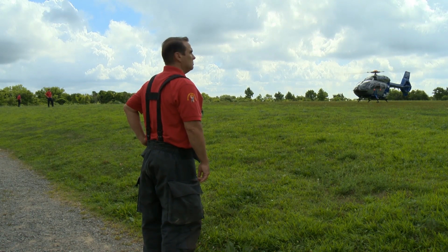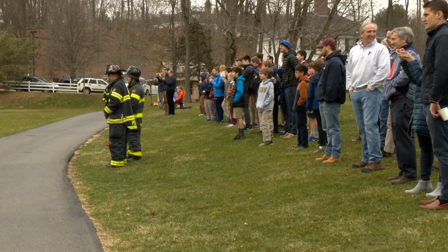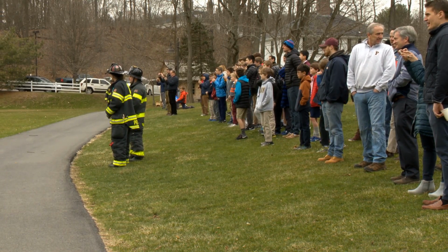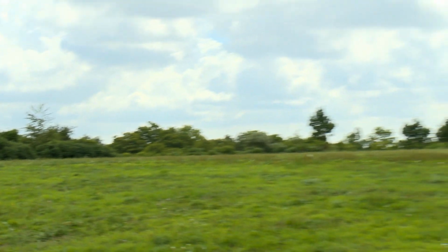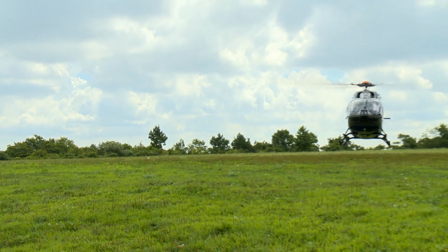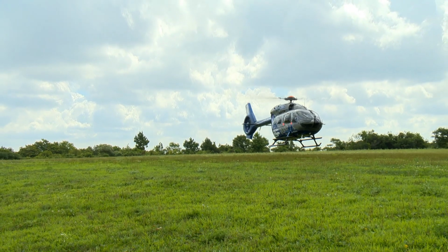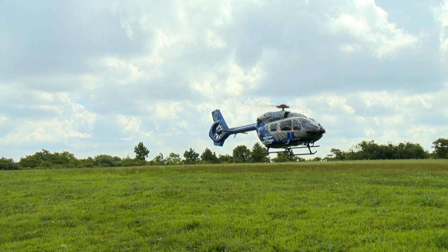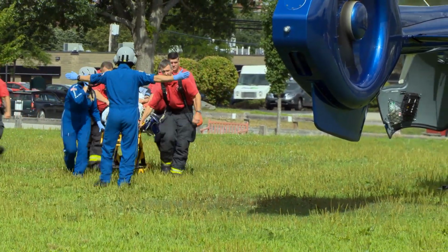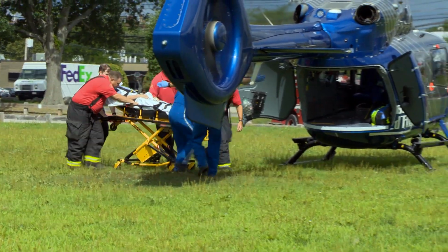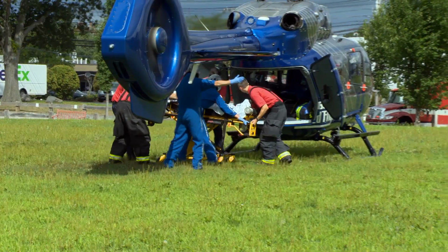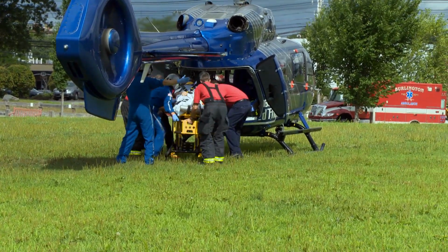LZ security must always be maintained. Bystanders near the proximity of the LZ are unpredictable and must be controlled. The LZ command is responsible for maintaining security during landing, loading, and until after the departure of the aircraft. The area around the tail of the helicopter should be monitored because it is typically out of the pilot's sight, and the spinning tail rotor blades are closer to the ground in the back of the helicopter.